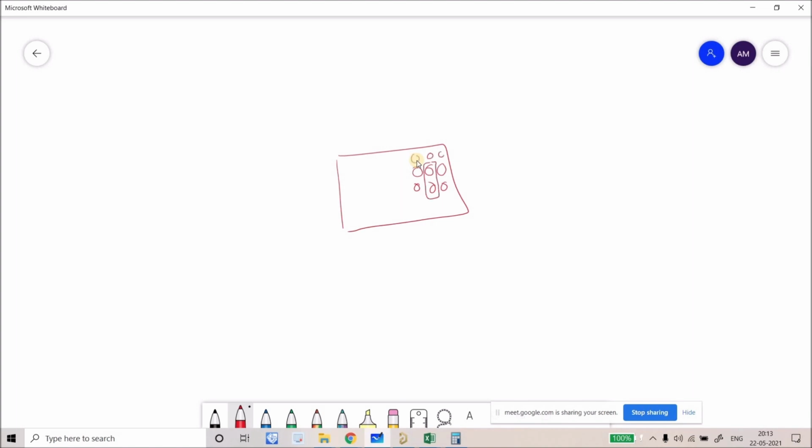Here also we have pads. Now we have to route this differential pair. What are the two options we have? One is we can place one via here, one via somewhere here. But let's suppose I have to route that outside, because it is again creating a clearance constraint between these two pads. Because these are differential tracks, what is the property of the differential track?